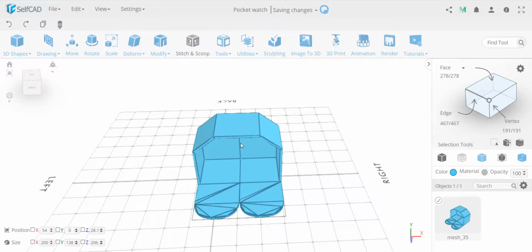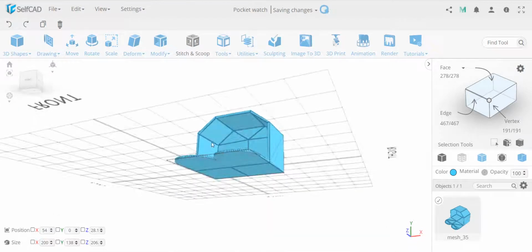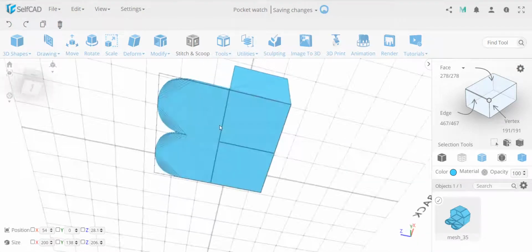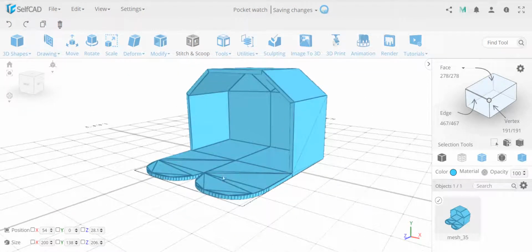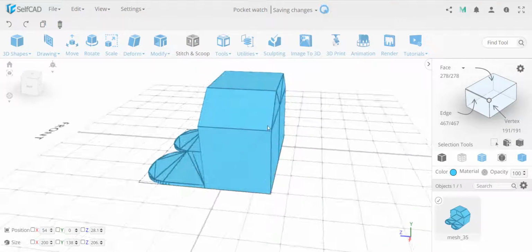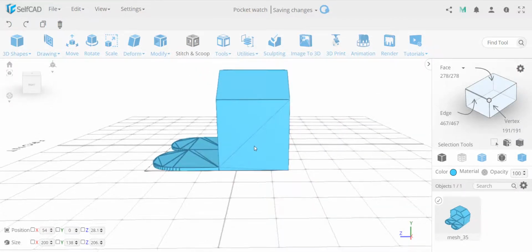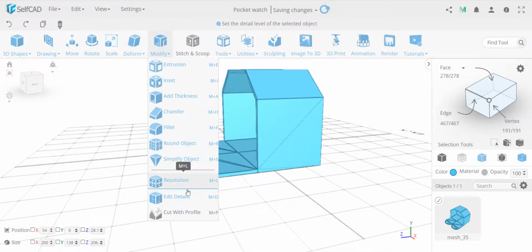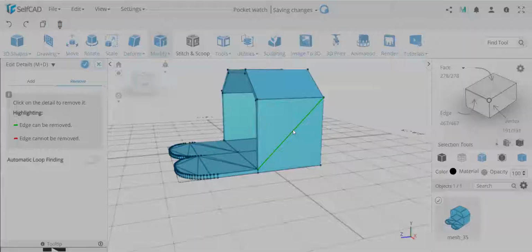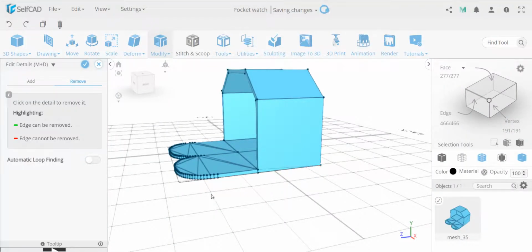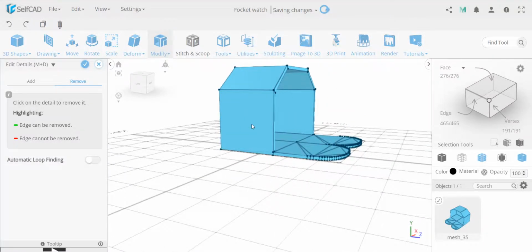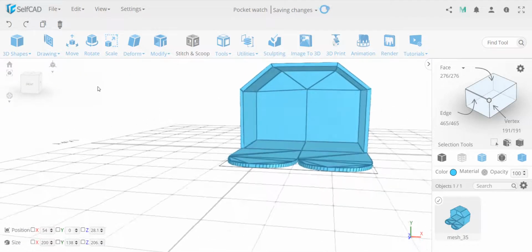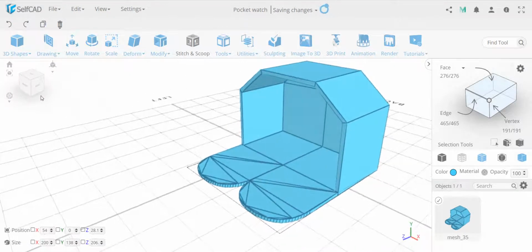When it comes to 3D, there are certain use cases where you need it. Like with this example, where 3D could be very helpful, we create an object like this in one piece. You don't have to use stitch and boolean. You can keep clean faces. And by the way, if this is not clean over here, this was added not from the fill polygon, but from the extrusion. So what I will do later is go to edit details to remove this. This you can't remove because it's needed, but I can remove this at least and clean this up. Other than that, you've got a clean mesh over here. So that's where this comes in handy.